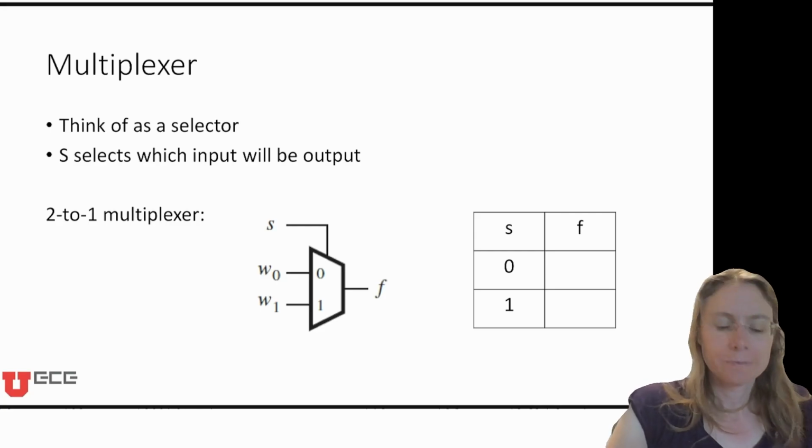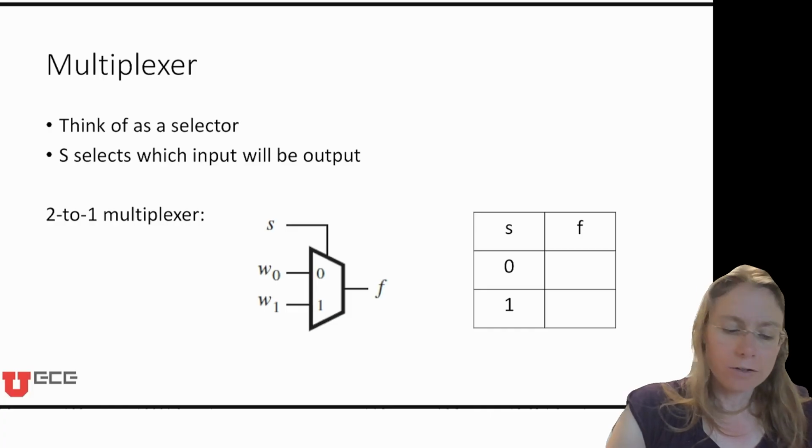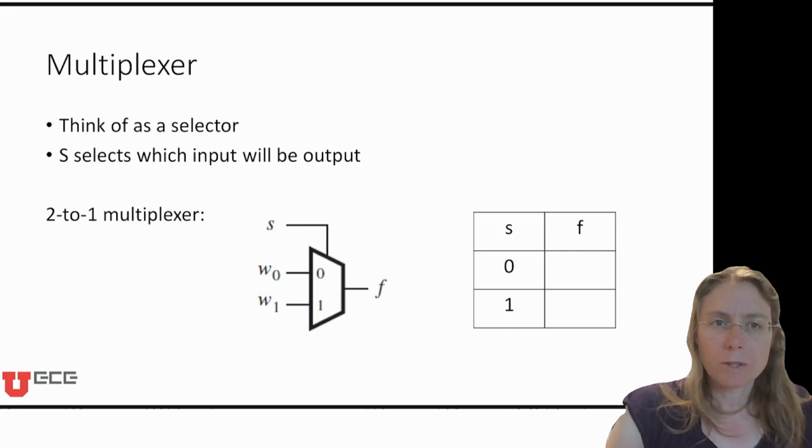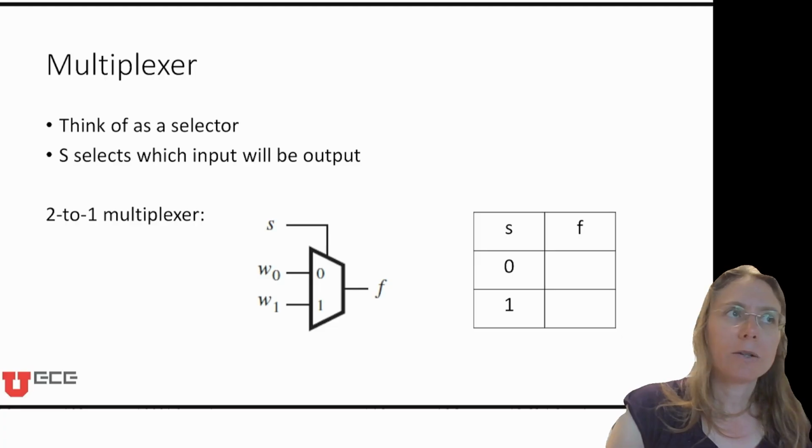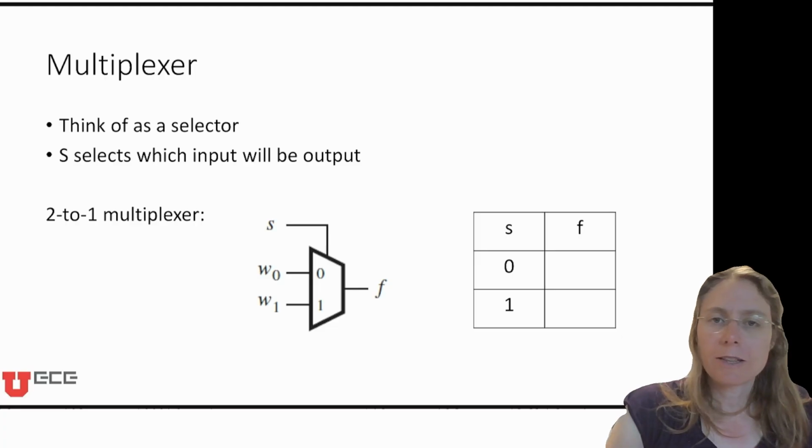Welcome back. Now we're going to learn about functional blocks of logic gates. So we're going to put together a configuration of logic gates that do a specified function for us. And we're going to learn about two specific ones today, a multiplexer and a decoder. And then we'll talk about chips that they make that can be programmed to do any possible logic you want because they have a configuration of gates in them. And those are called PLAs, or programmable logic arrays.